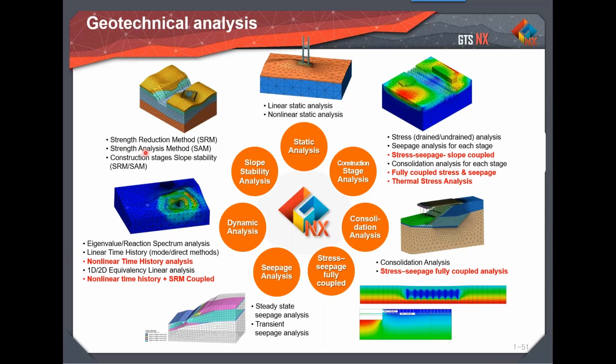So this is one of the important methods that will be very helpful in order to determine the local slope stability for your case. In the traditional limit equilibrium method, we develop various slip surfaces, and we need to calculate the stresses at the different slices using the Bishop method or Fellenius method or Janbu method and so on, right? But here, instead of using the Bishop method or Fellenius method and so on, in this software, we actually use the finite element method.